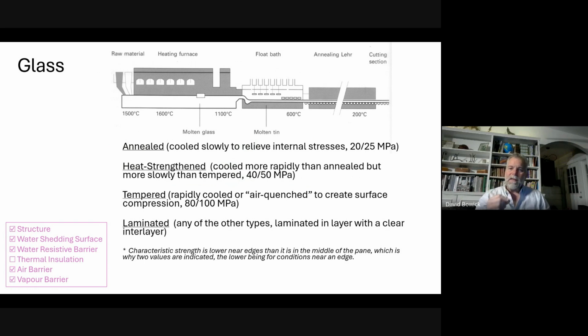Tempered glass, when it breaks, a crack propagates all through the glass very rapidly, and the glass completely shatters and voids the opening. That's because if a flaw gets through that compression layer into the tension layer, there's very high tension in that layer, and so it just forces the crack to propagate everywhere. So that's tempered glass.